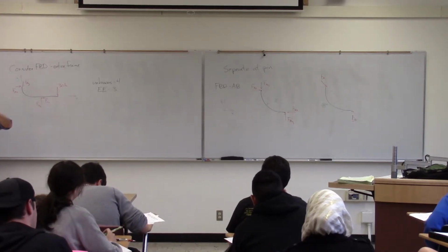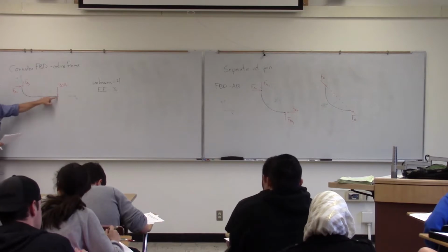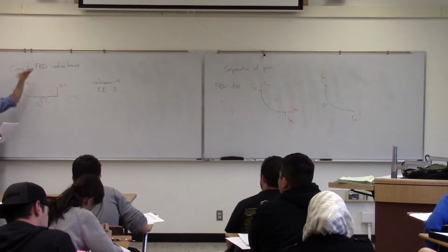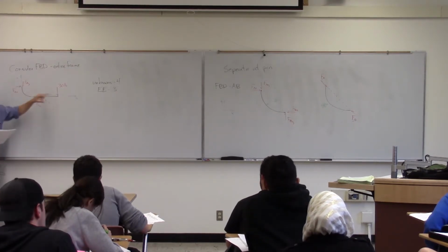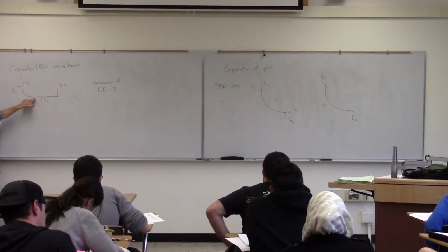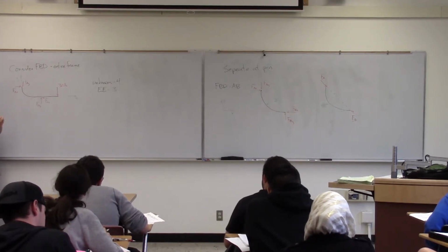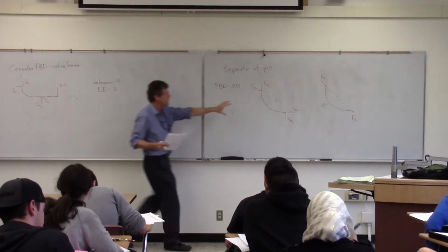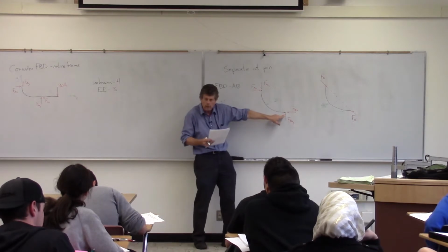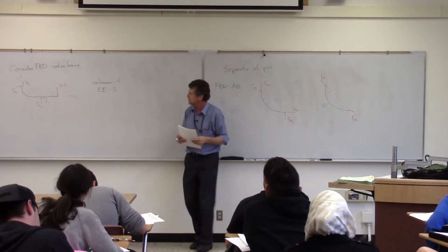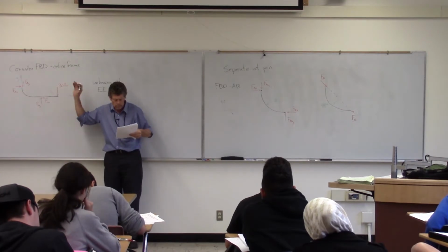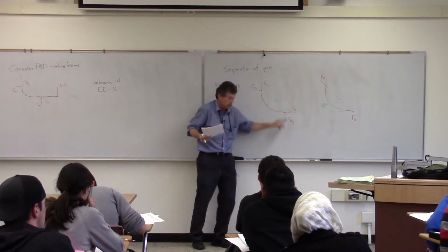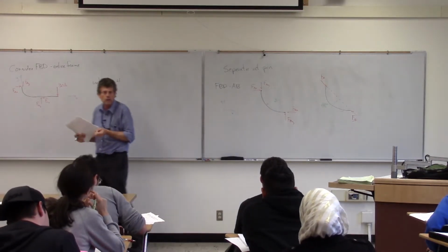So that's a mistake a lot of people make, and I'm glad you brought that up. When we draw that, yes, there may be pins all over the place. When we do trusses, basically there's going to be pins all over the place there. But in terms of that external boundary, that pin is not external to it. It's part of the contiguous structure there. So it doesn't show up here. It only shows up when I actually pull it away from that body. When I pull it away from that body, then I have to substitute in what the portion BCD is doing in terms of a set of forces. And since it's a pin connection, it can only be that unknown force, unknown direction.